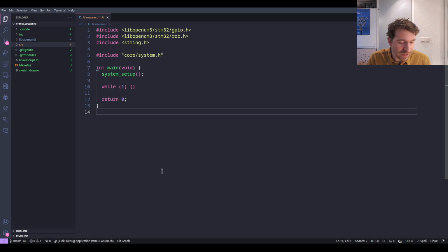Now, this is not always what you want to do. Often you want to try and delegate some of this responsibility to peripherals, because that means that you can use the CPU for other things, right? You can be running other code on the CPU while a peripheral takes care of generating a signal for you. We previously mentioned the idea of PWM. That would be one approach.